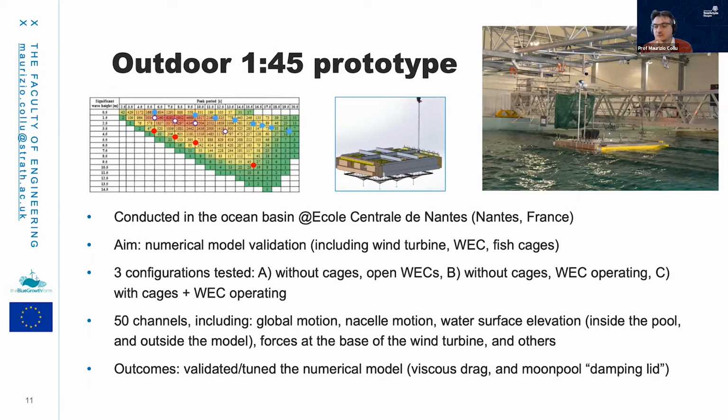Rather than the wind turbine, we had a fan and basically with a software in the loop approach, we had an external software calculating in real time what would be the force transmitted from the rotor to the tower of the wind turbine. And this was recreated, scaled, on the top of the tower, as you can see here, of the scaled model tower, so that we can capture what is the scale model motion and therefore compare it against our numerical model.